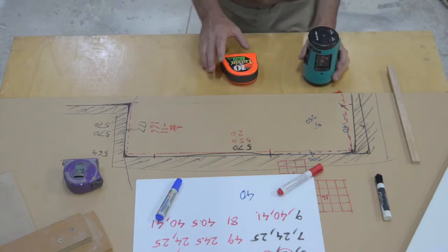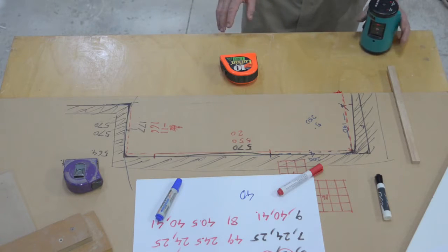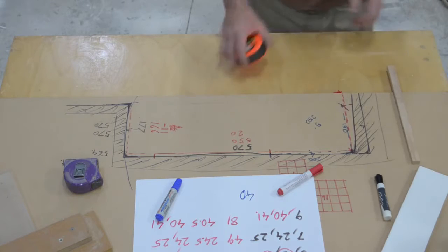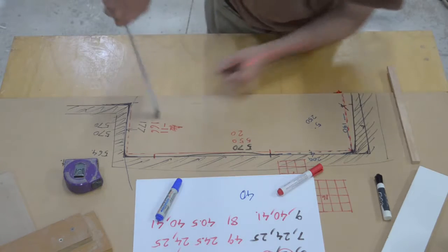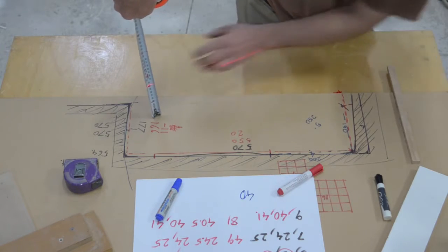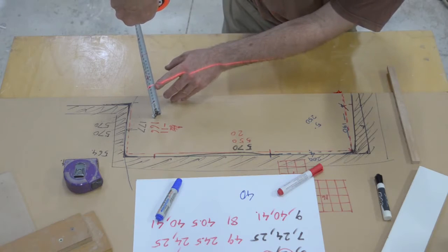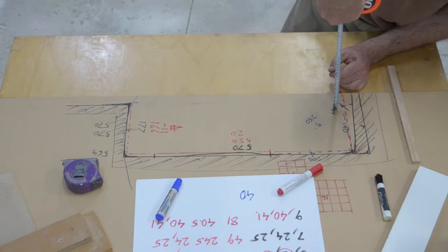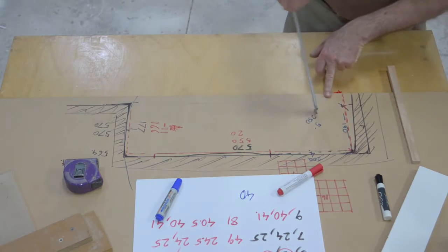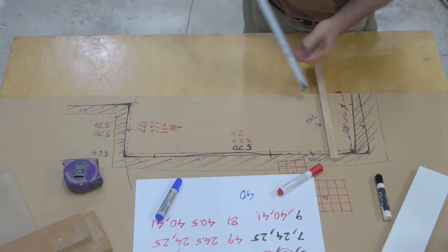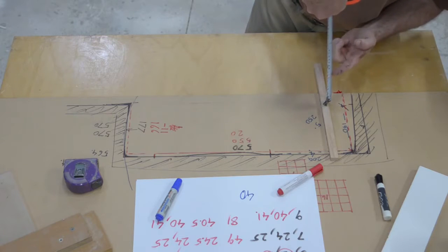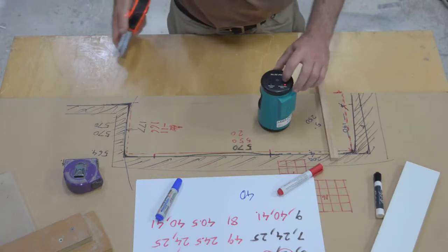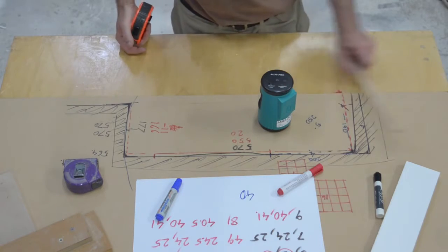Now I'll use that as an example by standing back here. I might put it on the other side. So I've just got, can you see that? Yes. That's showing 100mm or 101 there. And over here, the same. Of course, in this little space on the workbench it doesn't show up much. But if there was a variation in the floor of 10mm, it would show up with the laser. So a tool like this laser is very handy, but they are expensive.